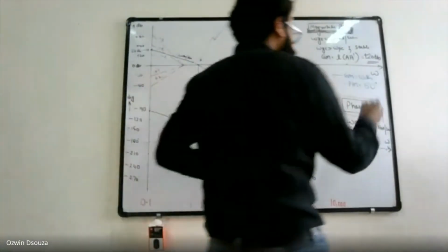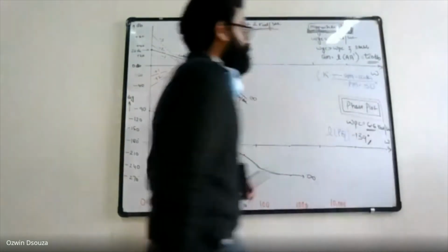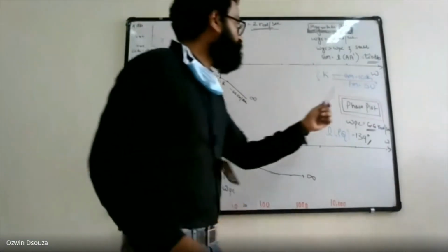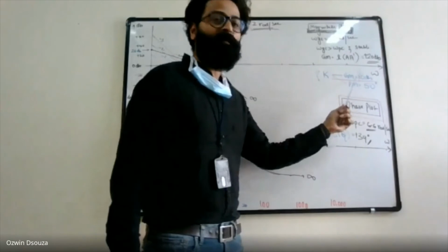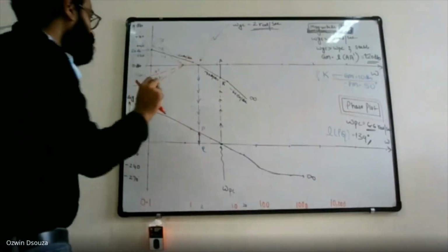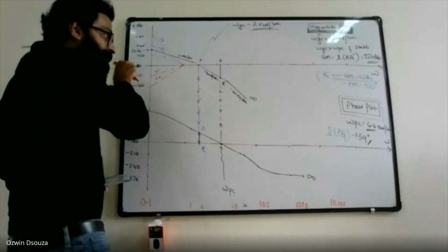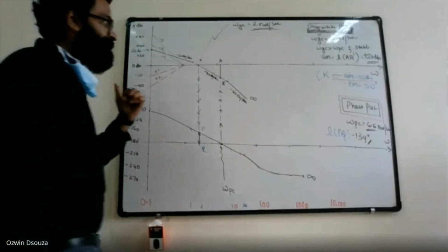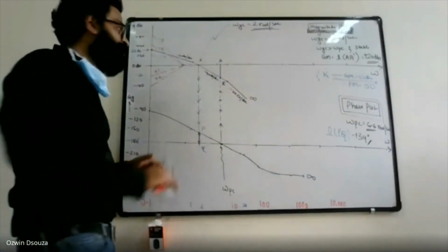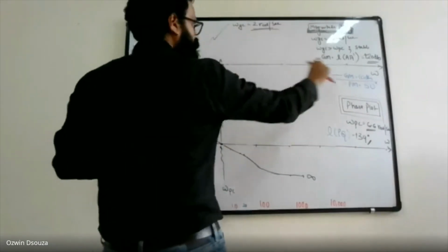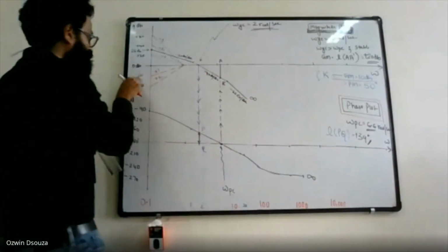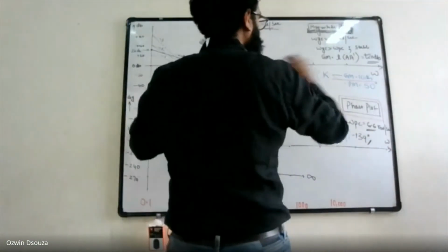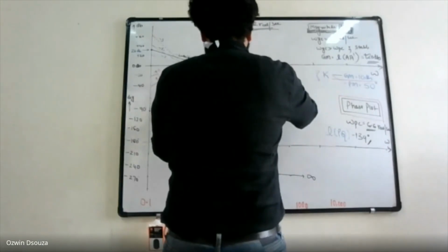First we will consider the first case, that is gain margin of 10 dB. So you have to look at the sign of it. It is plus 10 dB. So you have to locate plus 10 dB gain margin in your magnitude plot. Positive gain margin is found below the 0 dB line. So you have to mark plus 10 dB. This is minus 20, right? So exactly half, this itself is 20 dB, so exactly half you have to take.